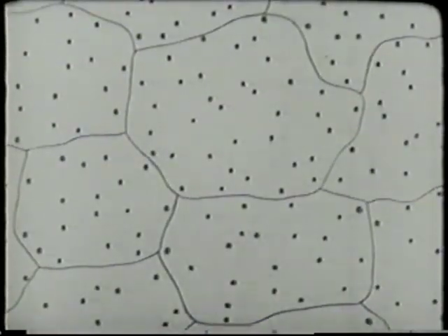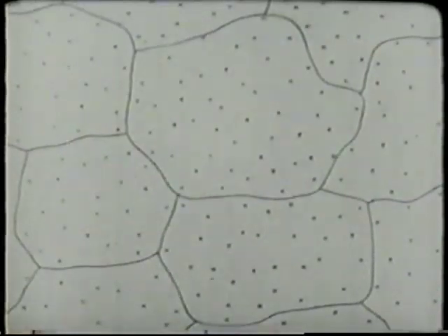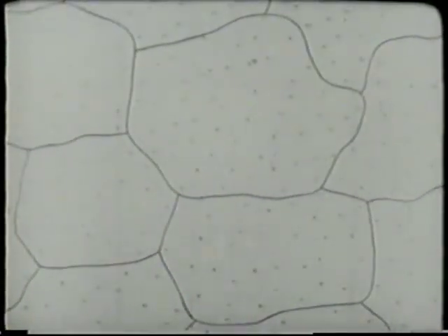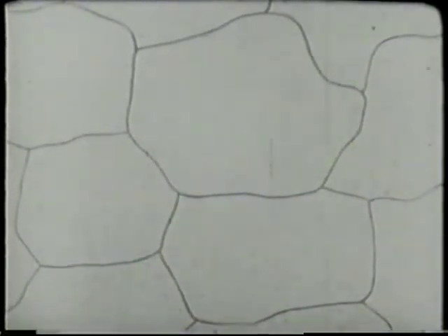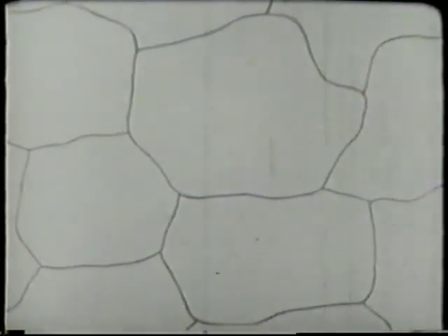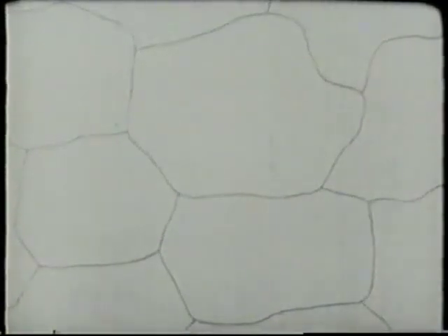In the solution stage of the heat treatment process, temperature is increased and the CuAl2 particles decrease in size as the copper gradually goes into solid solution with the aluminum. Subjection of the alloy to the proper temperature for the right length of time brings about the disappearance of the CuAl2 particles. The copper has now been largely dissolved in the aluminum. The solid solution is now retained or captured by a quick quench, which provides rapid cooling of the alloy.